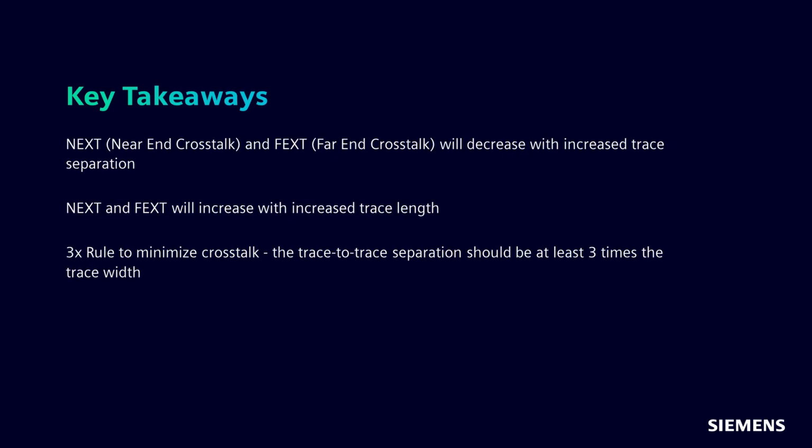To conclude this exercise, we have utilized HyperLynx SI to observe and quantify the effects of crosstalk, a critical signal integrity concern. We've seen how electromagnetic fields couple between adjacent traces and how this coupling leads to both near-end and far-end crosstalk. I encourage you to continue experimenting with different trace geometries, stack-up configurations, and signal characteristics within HyperLynx to deepen your understanding of crosstalk mitigation.